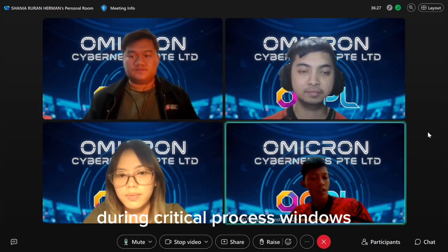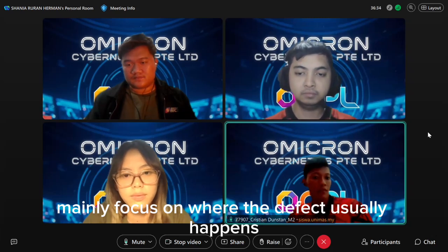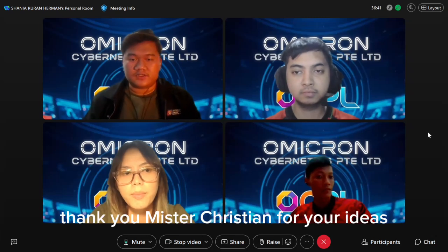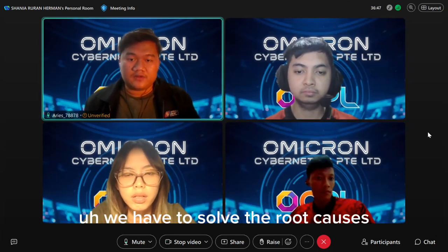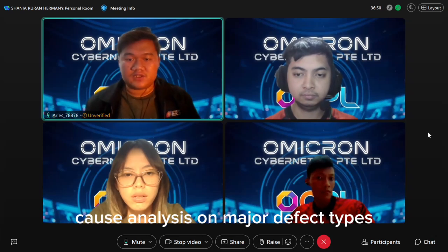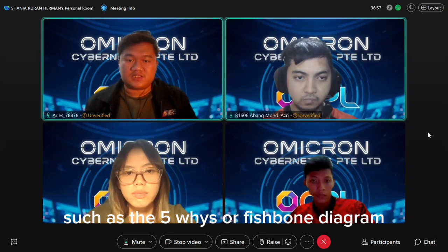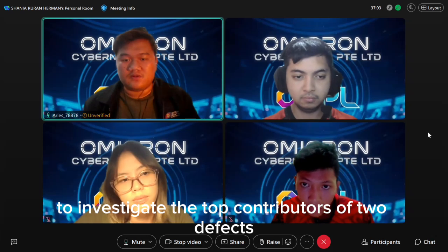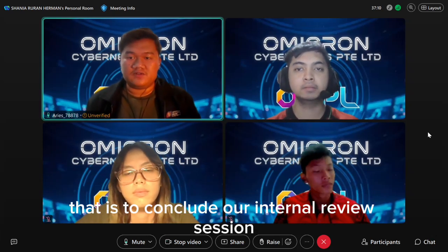I would suggest to increase the sampling frequency during critical process windows for tighter monitoring, mainly focusing on where the defect usually happens, in order to mitigate the problems and issues encountered. Thank you, Mr. Christian, for your ideas. So as for me, we have to solve the root cause analysis on major defect types, to conduct a structured root cause analysis such as the 5 whys or fishbone diagram to investigate the top contributors to defects.